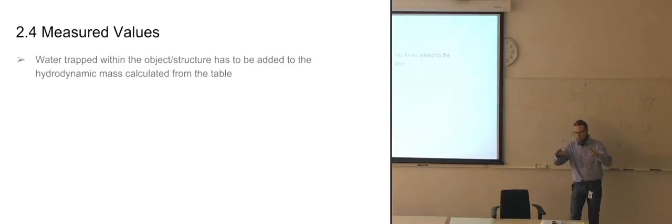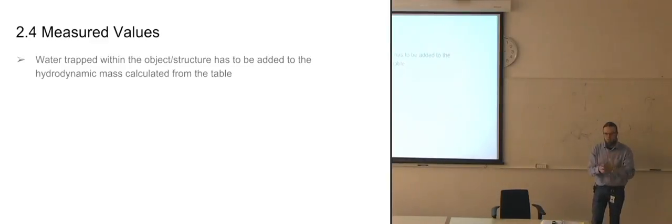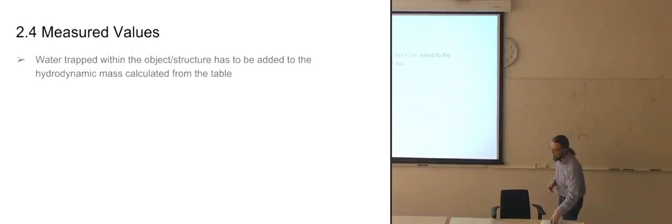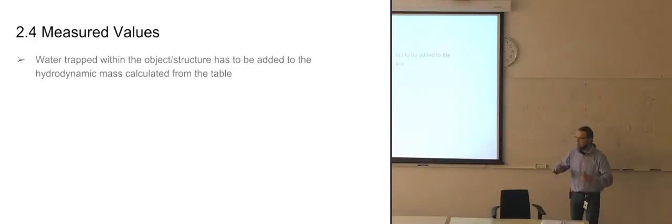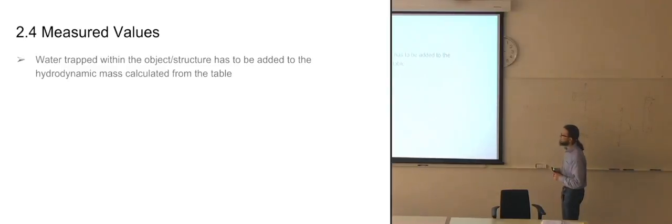Then it can shift a bit and get out of equilibrium, and the air trapped on the one side won't escape at all, because it's trapped in areas where it has no openings to exit the pipes. So you have to be very careful when you're doing these lowerings into the water. Make sure that everything gets fully filled with water.